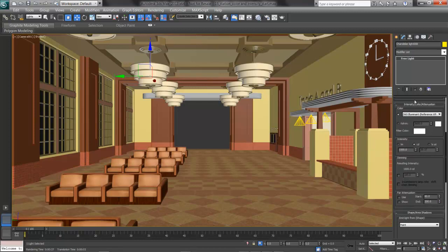It starts out at a D65 Illuminant, a reference white light bulb. What I'll do is switch over. Depending on the lighting that's in the space, I may want fluorescent, warm or cool, for example. I'll try first a fluorescent warm white and see how it looks. The intensity here right now is in candles, 1500. We can also deal in lumens, or lumens at a certain distance, especially if you're doing lighting analysis. I'll try a render and see what the color looks like first, and then adjust the intensity.